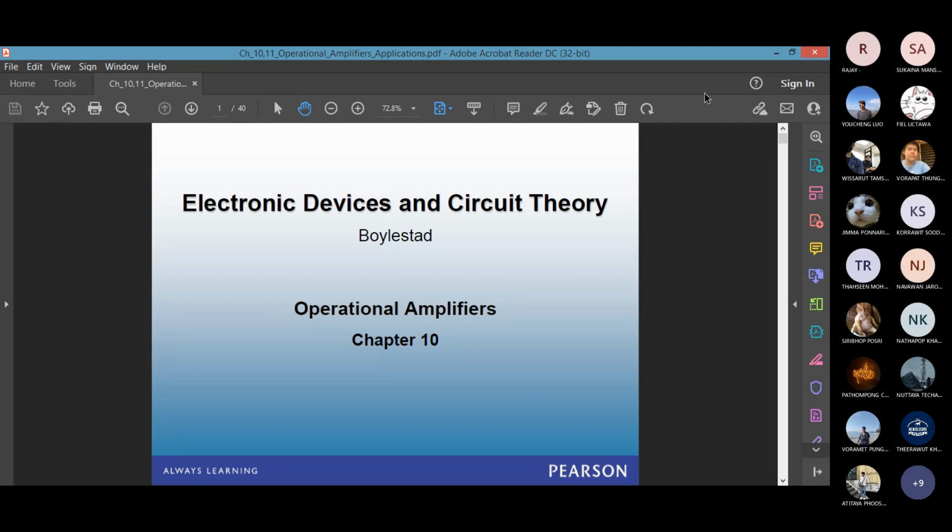You will see when we talk further about the gain, op-amp can operate in open loop mode and closed loop mode, but the useful mode is closed loop. In an open loop, when the op-amp output is not connected back to the input, the gain can be 20,000. An op-amp basically is a differential amplifier which has two inputs and one output terminal. So I just mentioned it is one kind of differential amplifier. Now we will start talking about differential amplifier.